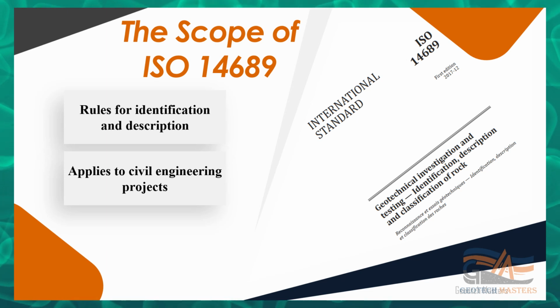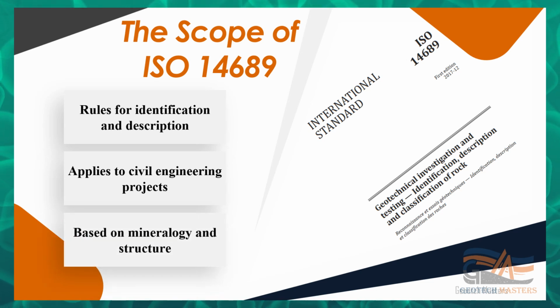The identification is based on several factors. We look at mineralogical composition, genetic aspects, structure, grain size, and discontinuities. It provides a system to describe these features accurately. However, please note that rock mass classification systems for design, like RMR or Q system, are outside the scope of this specific document, though we will touch on them later in the course.